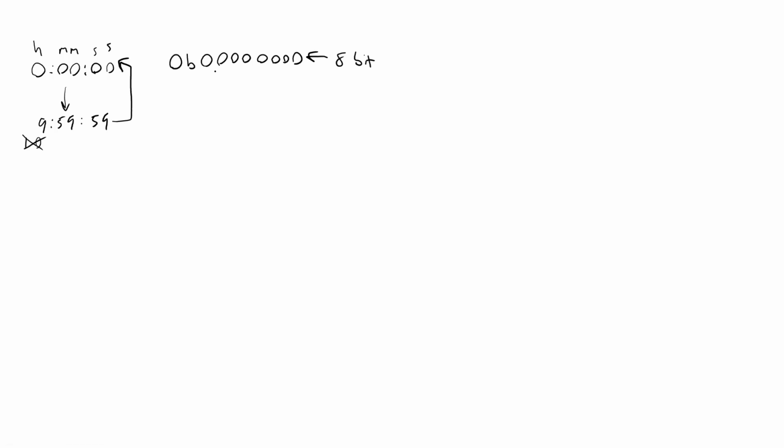So this is a timer that is storing 8 bits in what's called a register, or a specific location in the microcontroller's memory. So when that timer starts out counting at the decimal equivalent of 0, so this is the binary value here, decimal value over here is just 0, it's going to count up until all of the bits in that register are 1. So 1, 2, 3, 4, 5, 6, 7, 8, which is equivalent to a decimal value of 255 for an 8-bit timer. And then it can't go up any higher than that. It cannot count to 256 because it's out of bits. So it is going to overflow and wrap back around to 0.